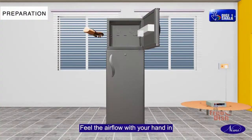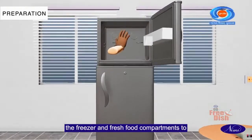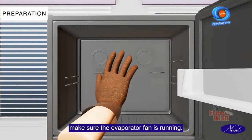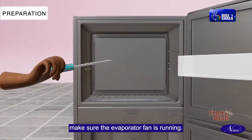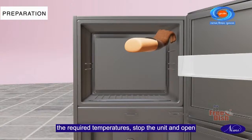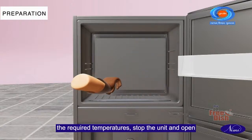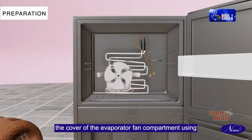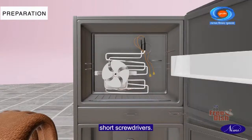Feel the airflow with your hand in the freezer and fresh food compartments to make sure the evaporator fan is running. If the refrigerator is running but not reaching the required temperatures, stop the unit and open the cover of the evaporator fan compartment using short screwdrivers.